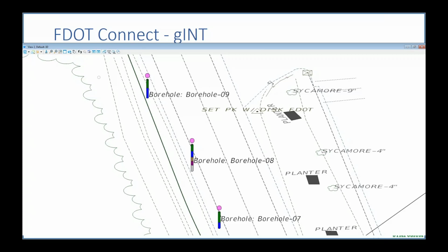I'm probably going to also add the AASHTO designations as well. So depending upon how they're classified for either roadway or structure borings, when they plot to the file, they will pass QC, because right now gINT just writes into the levels based on the lithology name, but that's more detail.